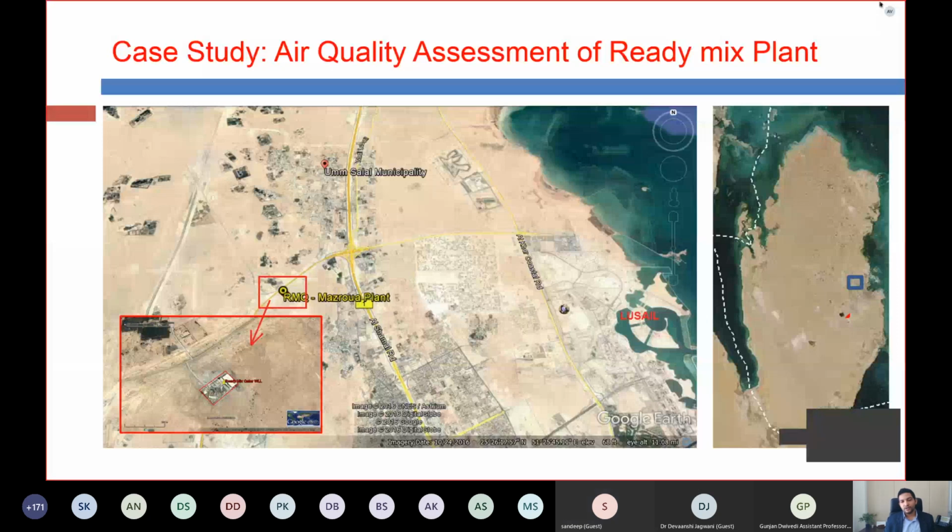First of all, we need to identify what kind of emission species would be there. Methane is one of the pollutants that is emitted from landfill sites because of the underground process. What USEPA have done is they have carried out methane testing on different field sites, and the concentration of methane is measured, and thereby they have come up with these emission rates. So yes, these emission rates for landfill facilities are available, and you can refer to the USEPA.